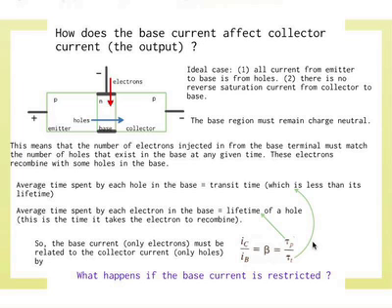Exactly. Yeah. So when this positive voltage gets built up, I'm decreasing the forward bias across the junction essentially. Right? This is almost like reducing the battery voltage. You see that? This is N-type, so if I put positive charges there, that's like decreasing the forward bias. Right? And if I decrease the forward bias, what happens? We know very well from our current voltage characteristics the current looks like that, right? So if I decrease the forward bias, the current goes down, right? Which means my whole injection goes down, which is exactly what you said.